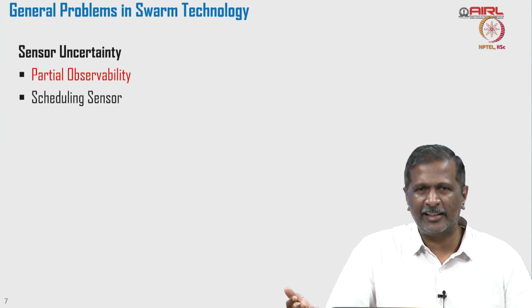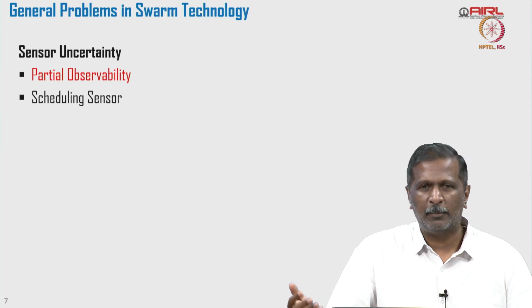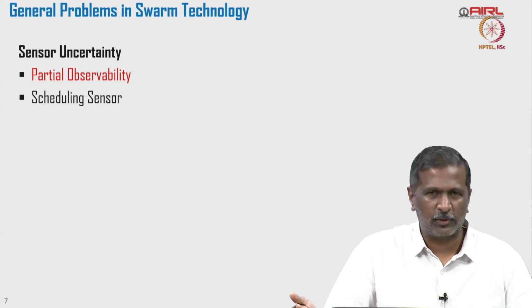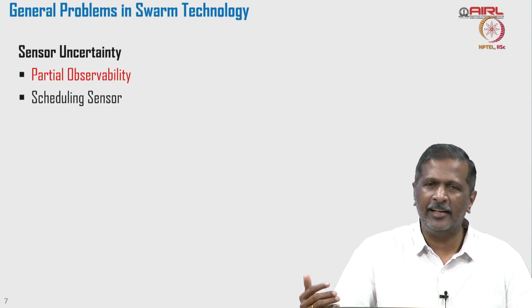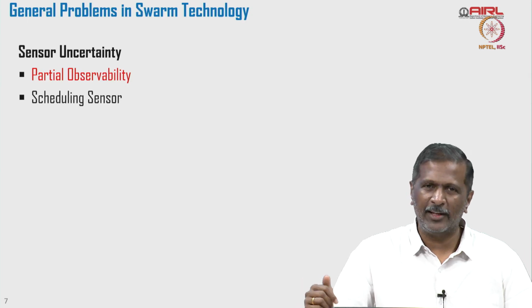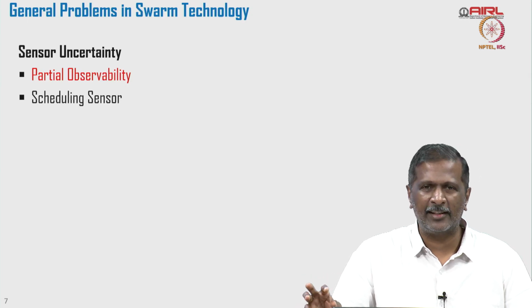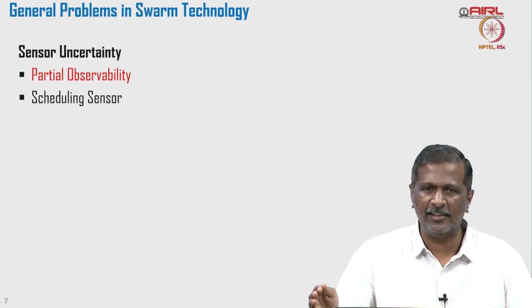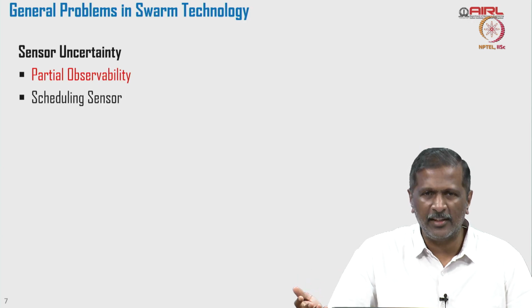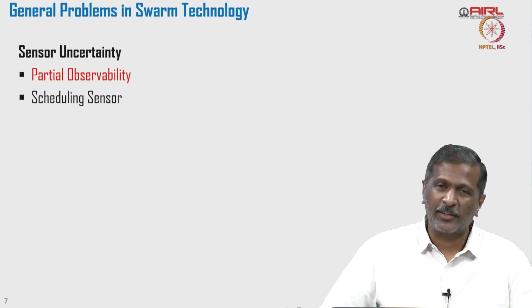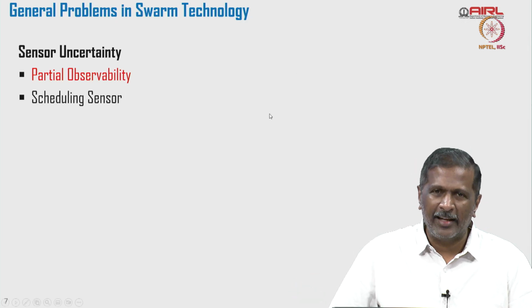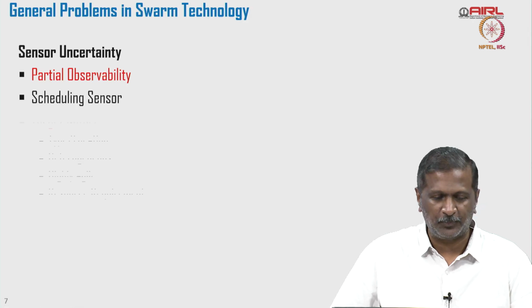See, if detecting fire, the best way is first look for smoke, then you find the local region, then look at the heat gradient, then you can approach, because just looking at camera alone is not sufficient because smoke will cover the entire region. It is not sufficient to see. Which sensor to use, and how do you schedule the sensor to get to the target, is a challenge.